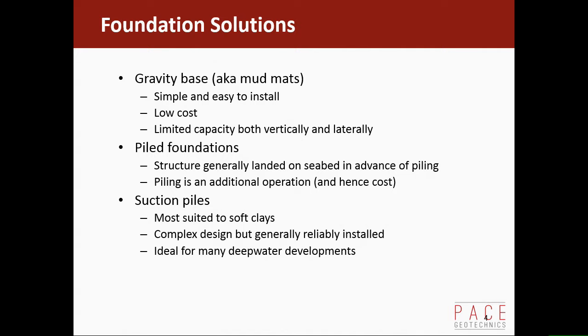On harder seabed soils, the lateral capacity of the foundation is essentially a function of the weight of the structure and the friction angle. So if you don't have enough weight, it slides. And you can engineer that fairly easily, but you do need to put weight in to achieve lateral resistance. Piled foundations are common, and they often are used to help achieve a required lateral resistance.